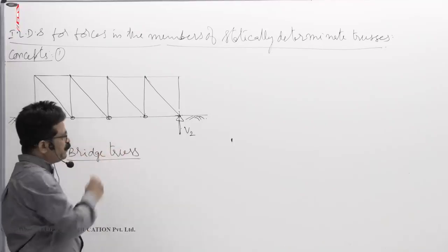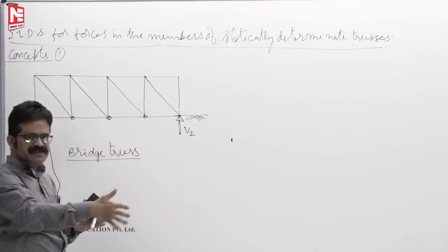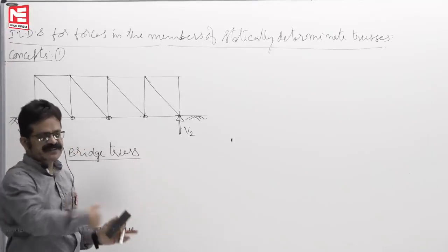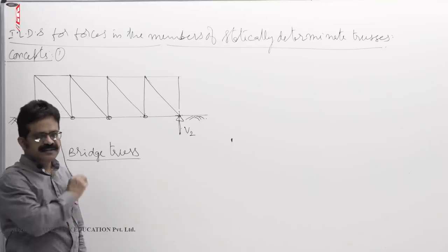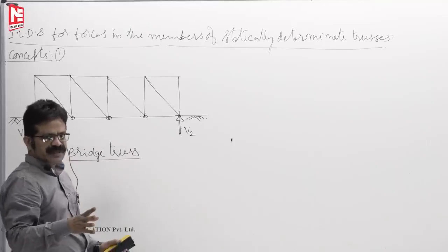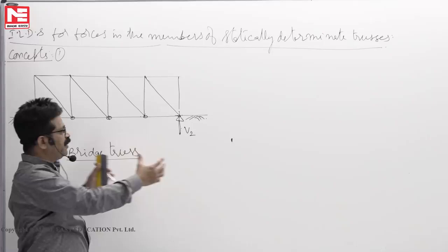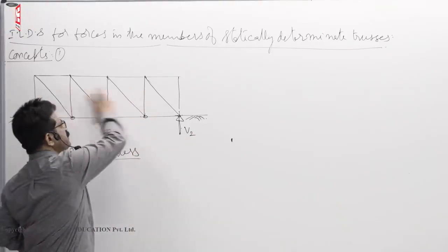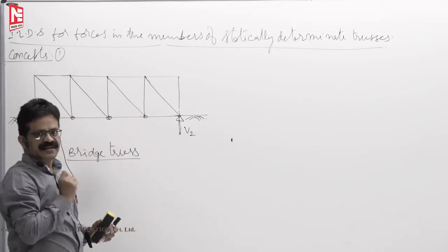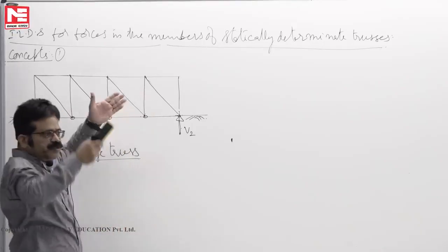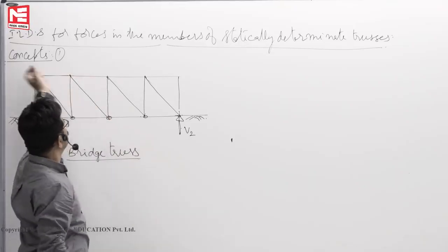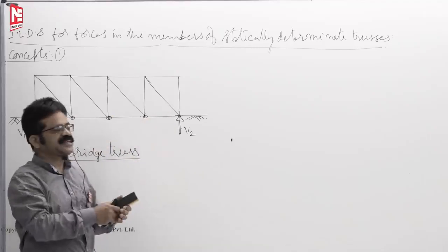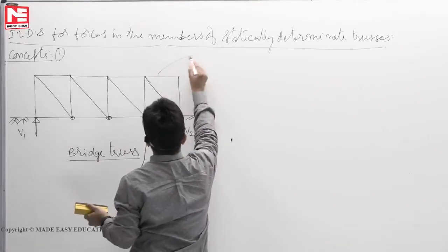Now assume that if you have a small span, when a canal is flowing, the canal span may be say 3 meters or 5 meters. Now beams you have provided. Now don't assume a canal, assume that a river is flowing. On the two banks of the river, you construct two piers, then trusses. A single truss we cannot use, two trusses must be there. On a single truss, we cannot keep a railway track if trains are moving. So two trusses must be there. So actually these are two trusses.